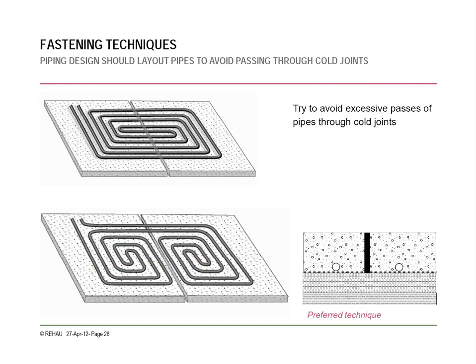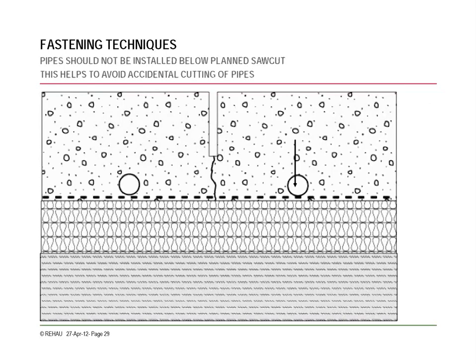So when you're designing or laying out the piping plan, take the extra time to think about where your control joints are going to be, where your manifolds are going to be, as we'll talk about later. And with radiant especially, as in most HVAC related work, if you just take a little extra time planning it ahead of time, it'll save you a whole lot of headaches.